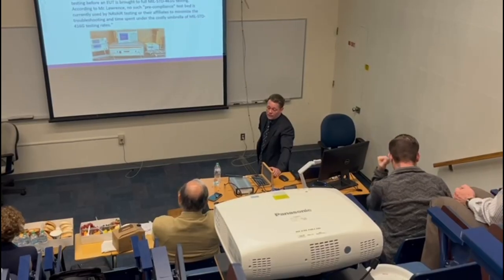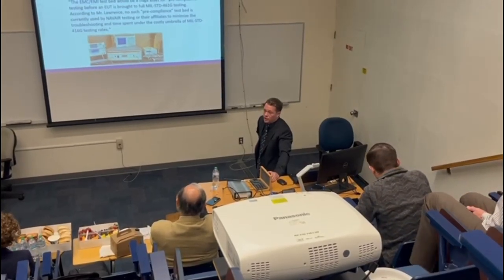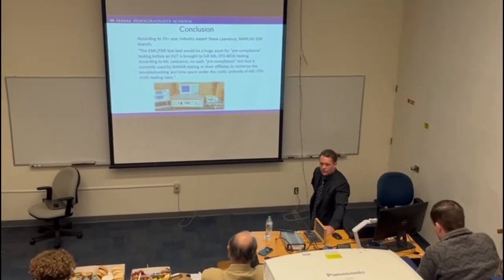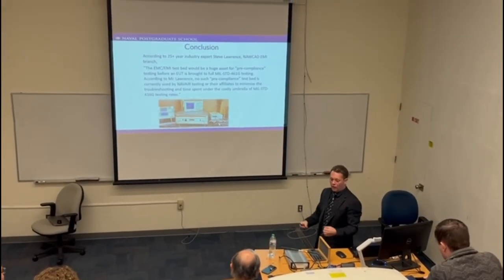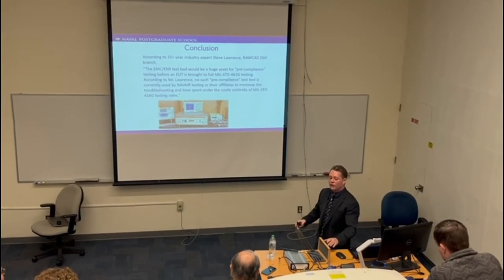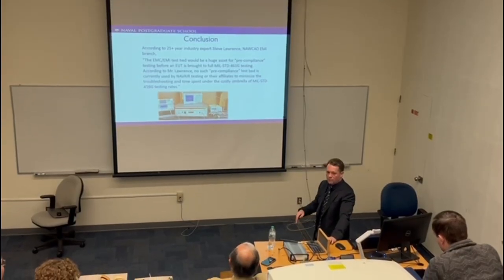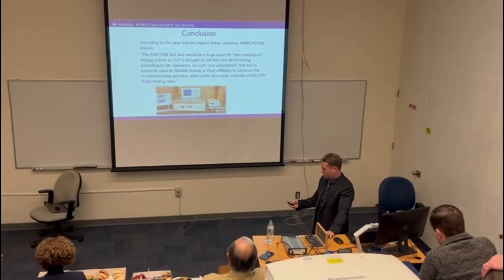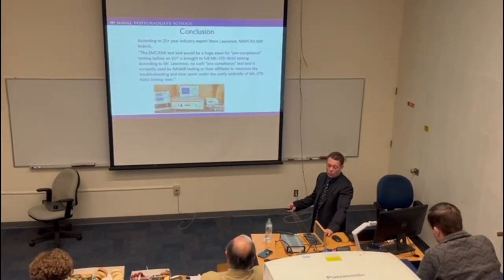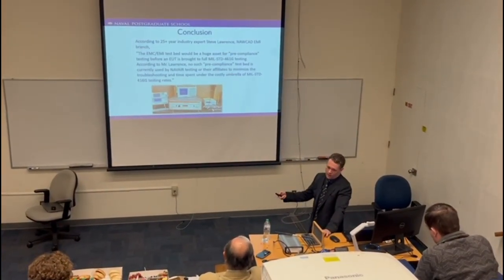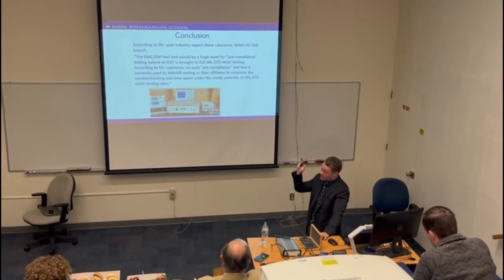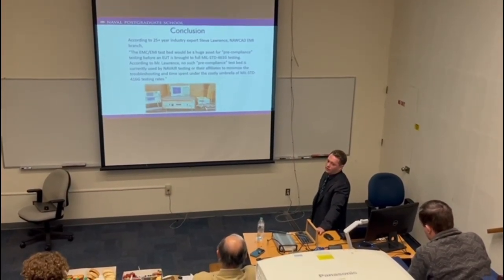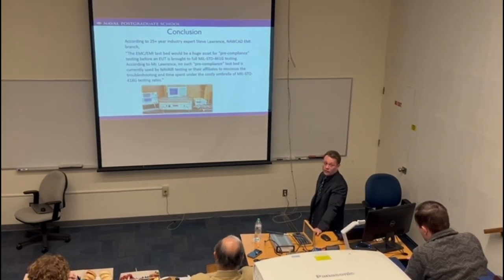Plus, if you're in the middle of making prototypes, you can adjust some of these characteristics of your circuit board layout, et cetera: bigger traces, more flux, smaller traces. There's a lot of things you can adjust to hopefully minimize the effects of these, shielding, filtering, hardening your system. It's good to know before it leaves the house. And even past this 461G testing, if you think you've got the whole thing beat, well, maybe not so much when it's on one of these destroyers with all that electromagnetic interference.